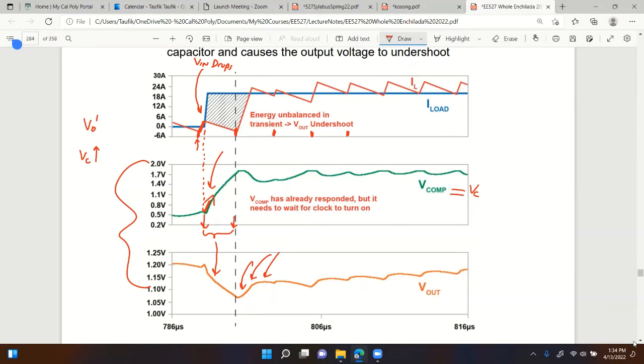If the error signal goes up, and you understand what we talked about earlier, duty cycle should go up right away, theoretically. But as you can see, it might happen that this change occurs when the clock has already started. Most likely that's the case, right? So even though the controller sees that, unfortunately it cannot do anything yet. It cannot take any action yet.